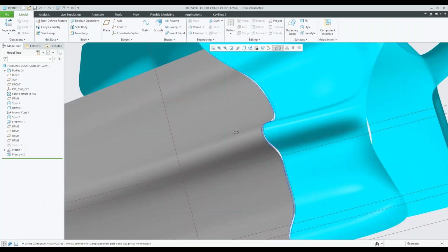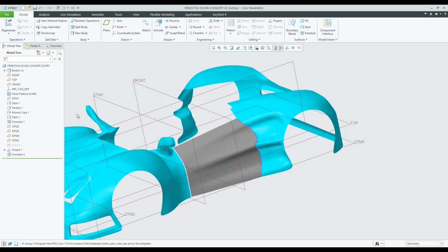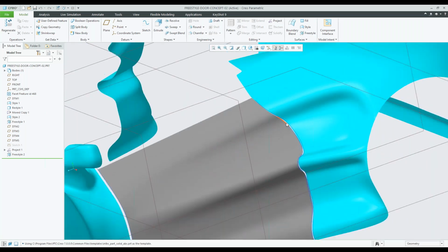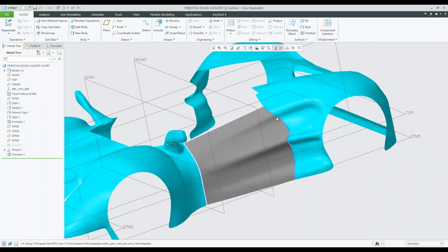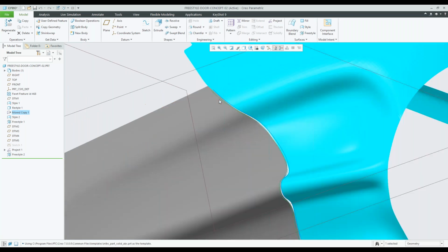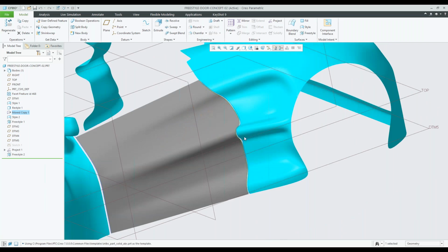And I just wanted to mention that you could do the same thing with geometry that's imported. So in this case, I imported an OBJ, went to Get Import, grabbed that OBJ file, and then once I was in there, I used the Reverse Engineering Freestyle tool to create a curve on that faceted geometry. Once I did that, I offset that curve out here to create a gap, and then you're able to actually link that freestyle mesh to that curve as well.